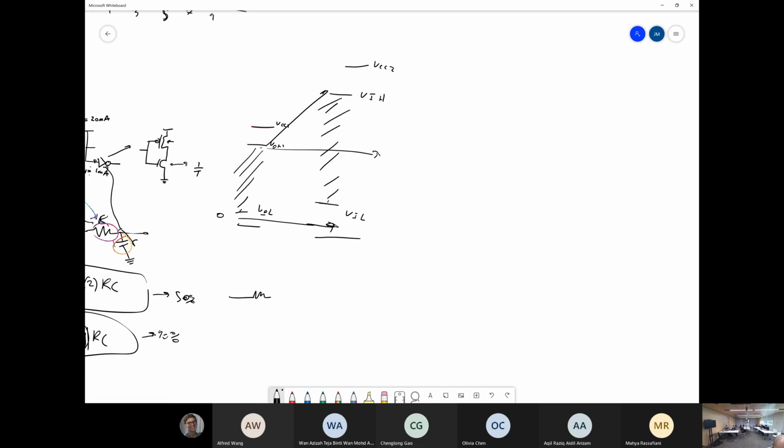Right? So if we put this here, and I'm able to draw, not like an absolute ape. Common emitter, right? We don't care about the specific biasing because we just care about it being on and off. So this is just a very high gain amplifier, basically. So if you put a 0, you get a 1. If you put a 1, you get a 0. It's an inverting amplifier. Right?